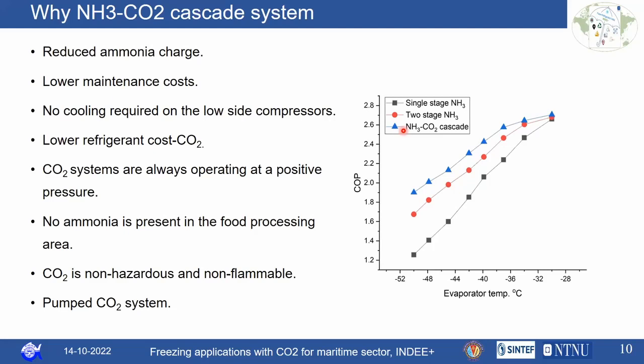Now, why this ammonia cascade system? As you know, these things have already been discussed, but we'll just go through them. The ammonia charge that is required, as you know, ammonia is toxic in nature, will be very low, and the overall maintenance is very low. And you don't need to have a cooling setup for the low side compressors. The cost of the refrigerant, that's the CO2 refrigerant, is very low. And the CO2 systems are always operating at a positive pressure. That is another important criterion we have to note, that the CO2 system will be operating at positive pressure, whereas a full ammonia system will be operating at -40 degrees Celsius below the atmospheric pressure.